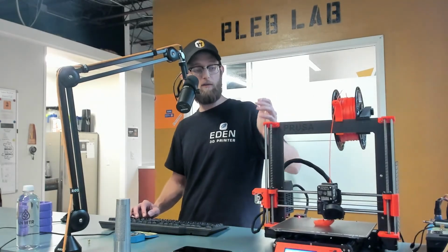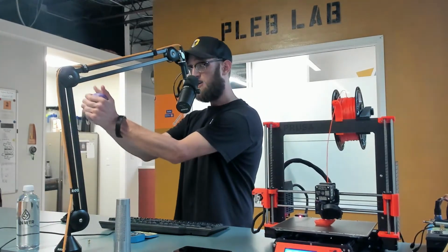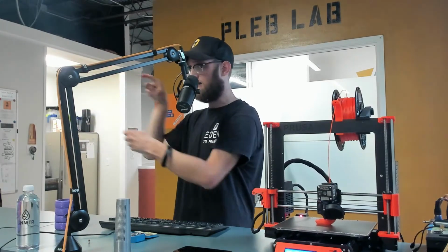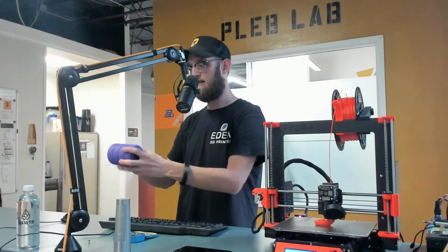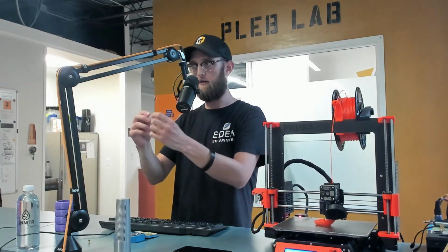Again, the tool head is moving. You've got a fan, you've got a direct drive, so the filament is being pulled in instead of pushing on a string. I find Bowden systems are good for PLA, but for TPU, your flexibles, you really need to pull them in instead of pushing from afar. Again, it's a rubber material. We have spools over there, but you would see the difference, hard plastic versus a soft rubber band-like material.